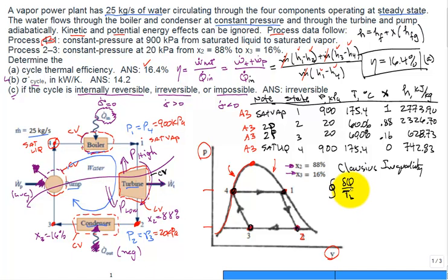It's a little funny notation, but this is thermodynamics. You're just summing up the heat transfer divided by the boundary temperature at which you're having the heat transfer, for the whole cycle, and that is equal to minus sigma dot of the cycle. When you had the inequality, it had to be less than or equal to, and now you replace it with an equality, with the minus of the strength of the inequality called sigma dot of the cycle.